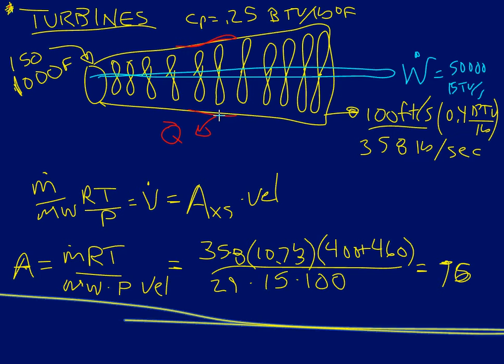So you wind up with this heat term coming out down here and lose some of your potential. Also, the heat can go into the gas itself, and you'll wind up with gas leaving hotter than it would otherwise if we try to run this turbine as efficiently as possible. And again, as efficiently as possible involves having very low gradient between the velocity of the gas itself and the velocity of the machine that it's turning. So that's a little introduction to turbines, and this is a gas turbine.